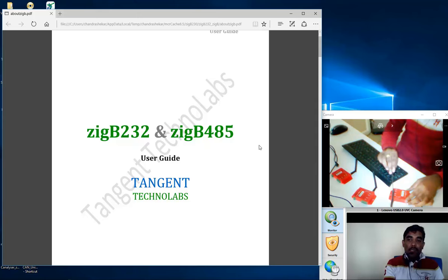The first LED is to indicate the power on status of the device. The second and the third LED is to indicate whether the device is functioning as a ZigBee coordinator or ZigBee router device respectively. And the final fourth LED is to indicate any ongoing data traffic on either the ZigBee or the RS232 channels.